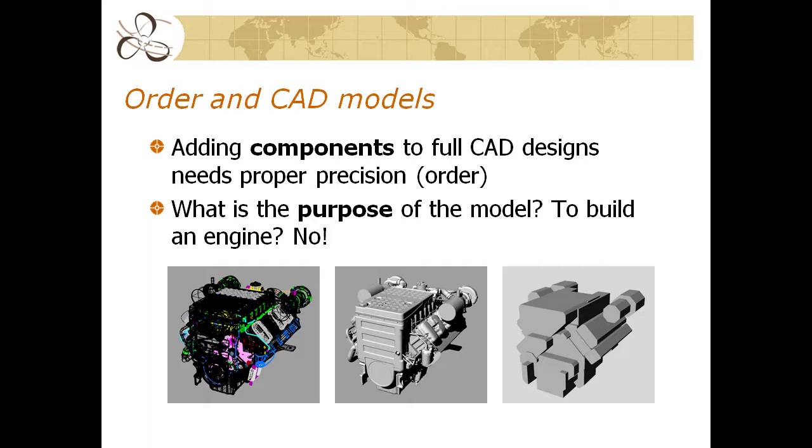You don't care about the internals of the engine. You want the connection points. You want those things. And I forget what the order of file size was, but it was about a 500% reduction of file size in order to be able to use this engine in a full ship design. So think about the purpose of the task before you try to capture the model.